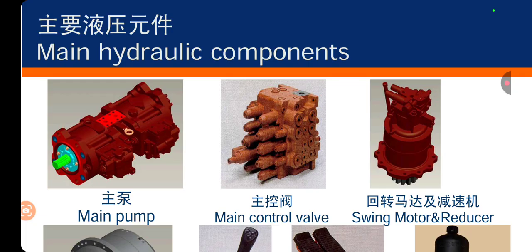Okay, it is connected with the shaft. It gets mechanical drive from the engine, and then sends the hydraulic oil to the control valve. This pump also has a sensing system behind that assembly. Okay, and in that case we have different valves which control the swash plate angle, so we can control the delivery according to the input from the operator from the lever. Okay, so I think it's enough about the main pump.